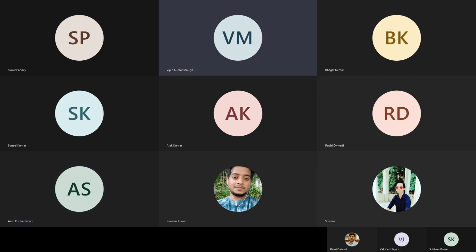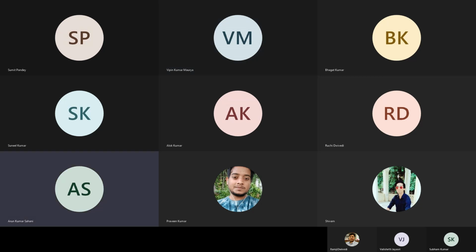You can simply think like I have a point. I have to compute its northing, easting, and up. So I need a reference point on the ground. For this point, I know the x, y, and z, but in reference to another reference point whose coordinates are x naught, y naught, z naught, or lambda naught, phi naught. So how will we do that? Is it clear? Yes, sir.